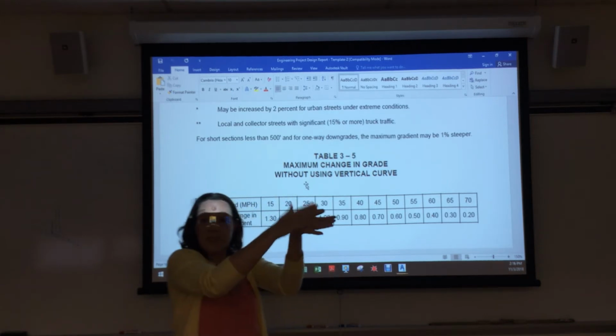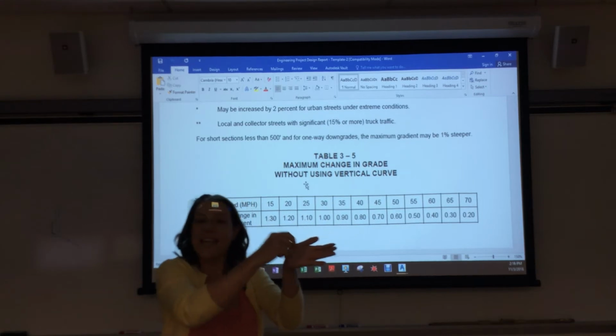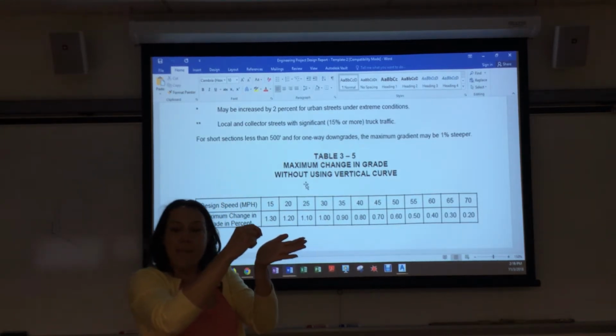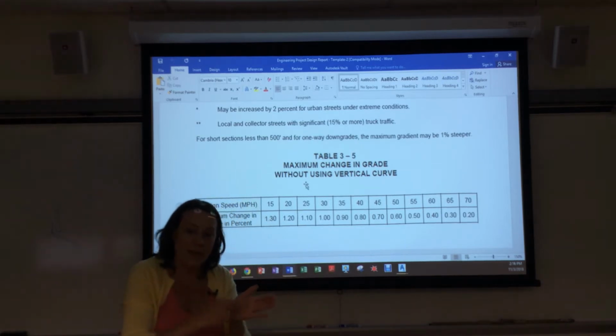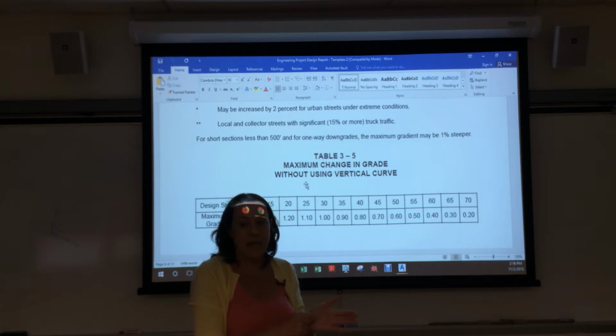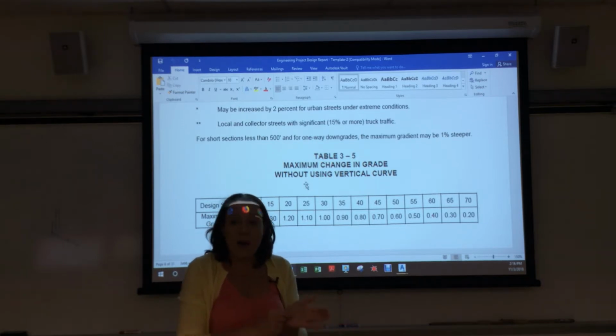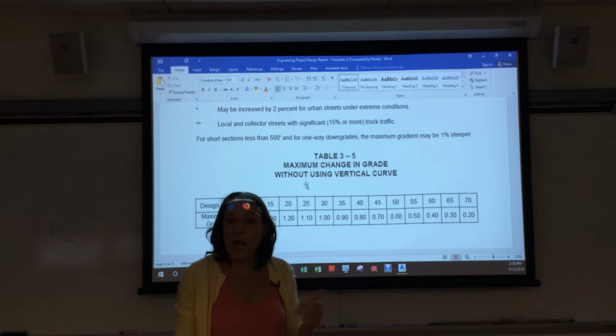Take this note right now. I don't know if I have it written down, but make sure you get this down. Roadways cannot have a minimum of less than 0.24% in Osceola County. That's the last time I looked. I always design my roads at least at a 0.35%. I've done 0.33 and 0.3.